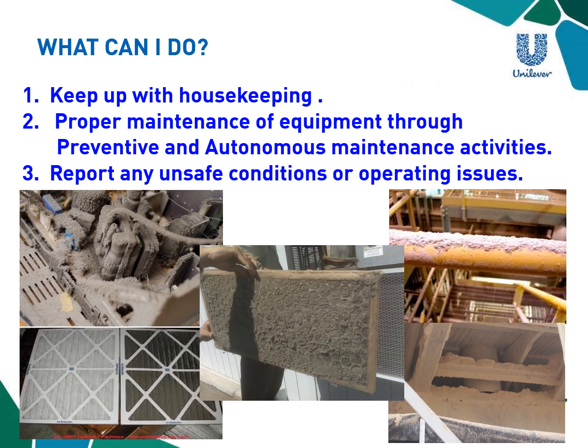So what can you do to help combat the risk of a combustible dust explosion here at Unilever Independence? Well, first and foremost, please keep up with your housekeeping. If we can work to eliminate the source of dust, then the risk of having a combustible dust explosion is virtually zero. Secondly, proper maintenance of equipment also helps. If you see a filter cartridge or something that's clogged with material and dust, swap it out sooner rather than later.